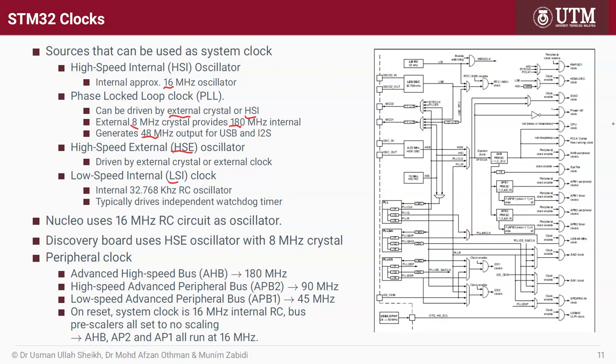Inside the chip, there's an RC oscillator. This is used to run the watchdog timer. Maybe we have time, maybe not, to cover what a watchdog timer is. But for now, let's say that the watchdog timer is a timer that looks after the system. So if the system crashes, the watchdog timer can restart it. It can somehow detect a stuck microcontroller and reset the processor. This is quite useful if you want a reliable system that can restart itself.